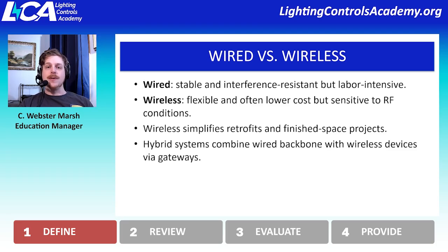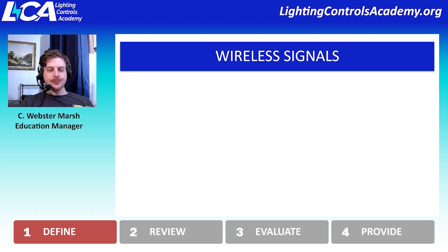If the corridor is hard to modify, it's an existing corridor, and you just want to add new lighting controls capabilities to the space, you might add wireless to that system to be able to give more expanded capability to the lighting in the corridor, but the rest of the building might remain wired for some reason. So thinking through where you're going to be using wires versus where you're going to have a wireless communication is something that's worth keeping in mind as we go through this.